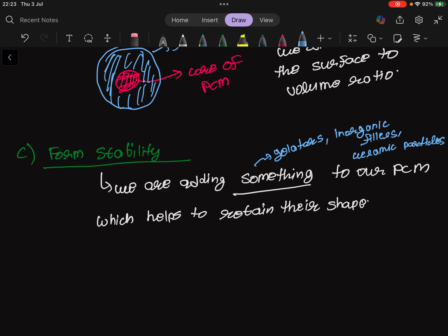We can have interaction between the PCM and the confinement, and we need to take into account which materials we are using. So if we have an alloy PCM, basically aluminum, silicon, copper, or iron, which is embedded in steel as shell, then iron and aluminum interact quite a lot. That is, they have good affinity.